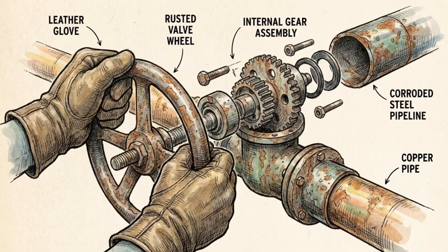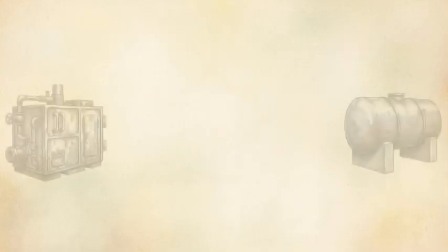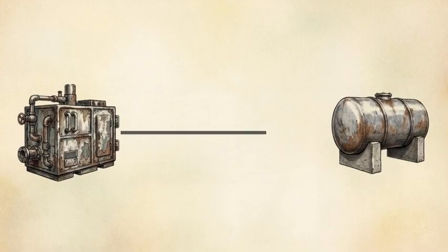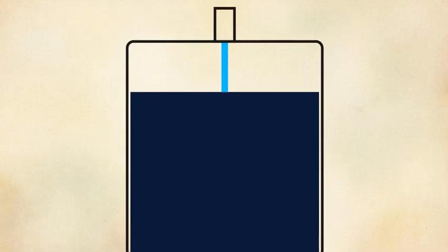The immediate trigger for the disaster was a routine maintenance task. Workers began a water wash of a nearby processing unit to clear blocked pipes. That processing unit was connected directly to tank E610 through a shared network of pipelines. A mechanical pipe stopper and a safety valve were in place to isolate the water. However, both failed to seal properly due to a lack of maintenance. Without the nitrogen counterpressure to repel it, the water flowed through the broken valves and poured into the tank.